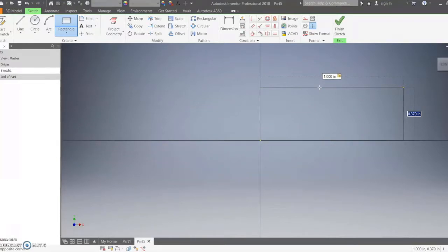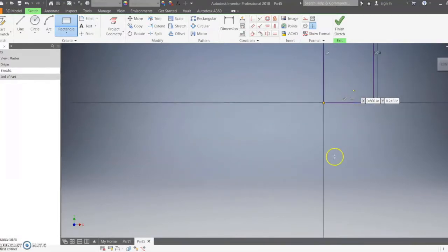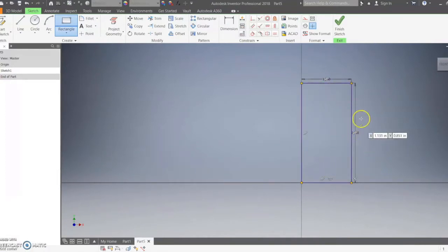As you can see now, it's highlighted. This will be 2, it's 2 inches tall. When you press Enter, you have your 2x1, 2 inches tall by 1 inch wide. But of course, a 2x1 has to have a thickness to the metal. Otherwise, this is literally just a 2D sketch. So we can add a thickness by having the same figure but offset a little bit inwards.